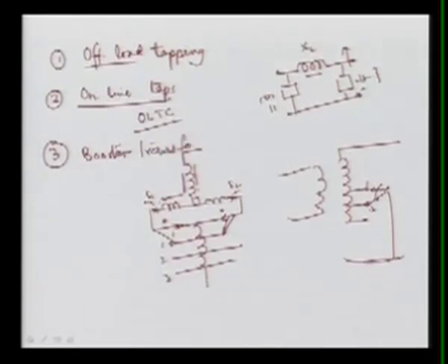Booster transformers are basically nothing but, if you have a transmission line, let's suppose this is a transmission line, and we inject a series voltage in the transmission line. That value comes from the transformer, and we have some tappings here, different tapping voltages that we are adding.